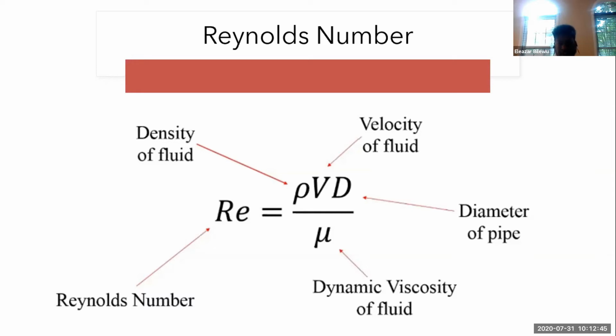In our specific case, we just use the simple formula of density over viscosity of fluid, with density just being 1 as a constant. So just 1 over viscosity of fluid. So you can already see there's an inverse relationship when running these simulations and plugging in numbers in this formula. If you want to increase the Reynolds number, you would decrease the viscosity. Whereas if you want to decrease the Reynolds number, you would want to increase the viscosity of the fluid.